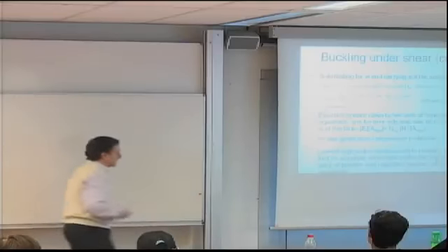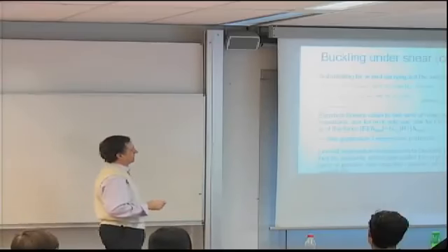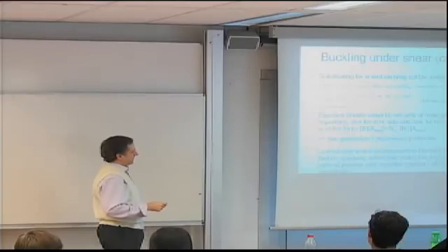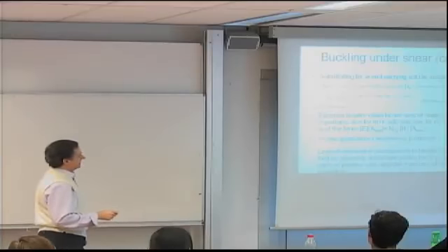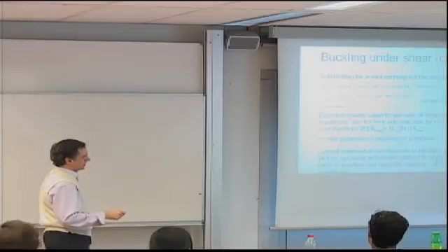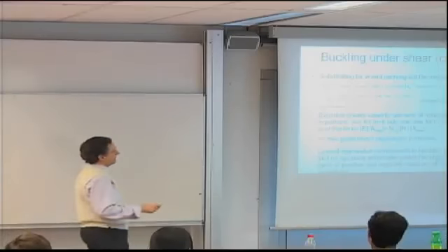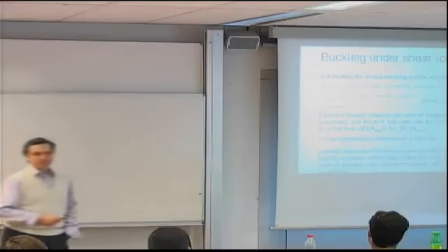And it turns out when you try to write it out expansively, you find that it breaks down to 2 sets of equations, one for m plus n odd and the other for m plus n even. And each of those sets of equations will look like this. Basically, I have a matrix E multiplying my unknown AMNs, my NXY, which is the buckling load I'm looking for eventually, then another matrix H, which involves just the aspect ratio and coefficients of m and n, and again my vector of unknowns.